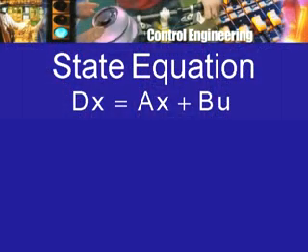Now, it is not necessary to do this, or rather there is another way of doing it which involves the apparatus of matrices, and as I told you, you have probably learned a little bit of matrix theory and some ideas from matrix theory. They can be used for control system purposes as follows. The two first order differential equations, as I mentioned to you earlier, can be written as a single vector equation dx equals ax plus bu,